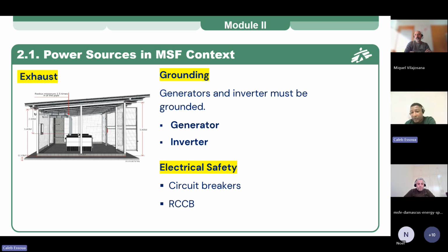Okay, you have two questions. Surge protection device, how does it work. The name also tells us that when there's a strike, this surge protection device gathers all these surges in the circuit to send them to the ground. Because if you see the surge protection device, you have this main power that comes in, and you have this ground line that is connected to the grounding bus bar.